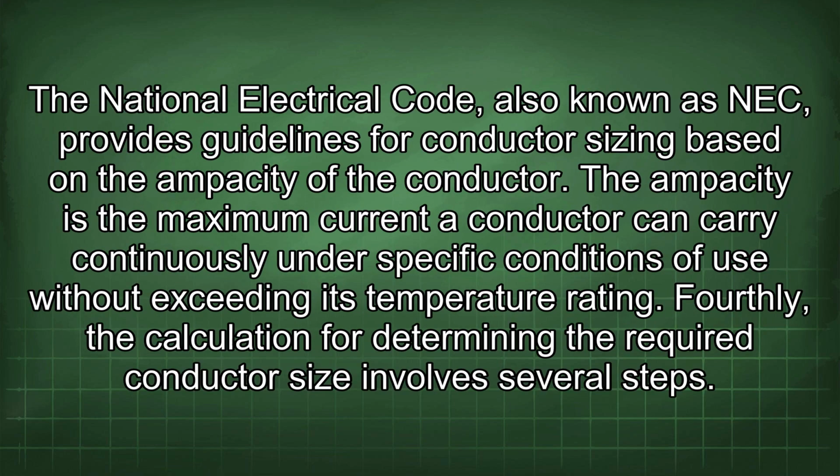The National Electrical Code, also known as NEC, provides guidelines for conductor sizing based on the ampacity of the conductor. The ampacity is the maximum current a conductor can carry continuously under specific conditions of use without exceeding its temperature rating. Fourthly, the calculation for determining the required conductor size involves several steps.